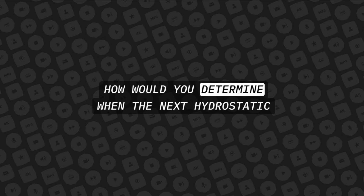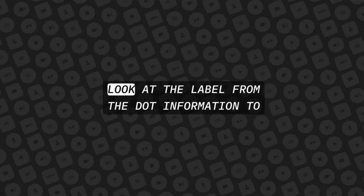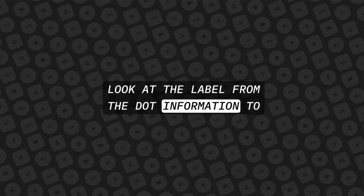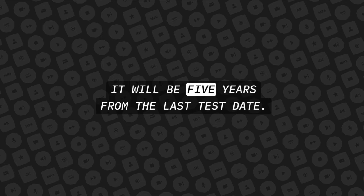How would you determine when the next hydrostatic test is due on a portable fire bottle? Look at the label from the DOT information to determine when the next test is due. It will be 5 years from the last test date.